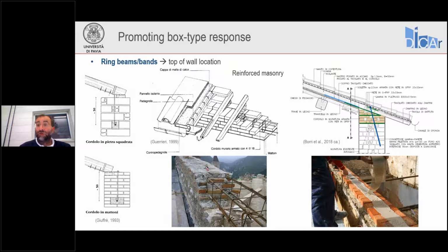And this is to improve connection with the masonry wall to avoid sliding and other problems at the interface between the reinforced masonry beam and the existing masonry. This is especially necessary if the existing masonry is of not very good quality. In some cases it may also be necessary to improve the quality of the masonry material, at least locally around these anchorages, for example, by joint repointing, grout injection techniques, whatever is necessary to reduce the vulnerability due to the material constituents.